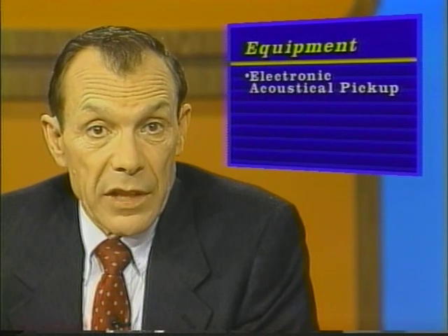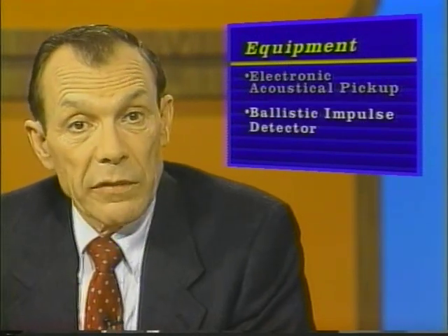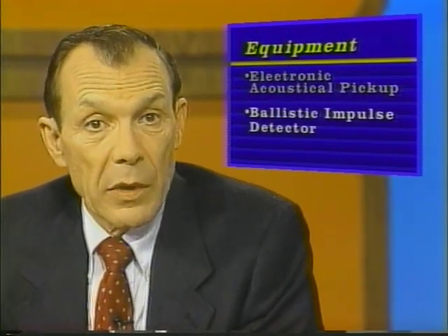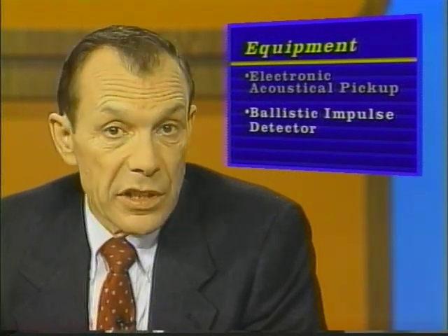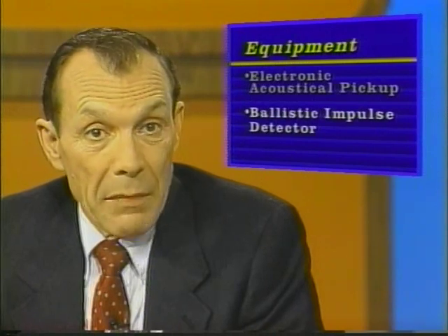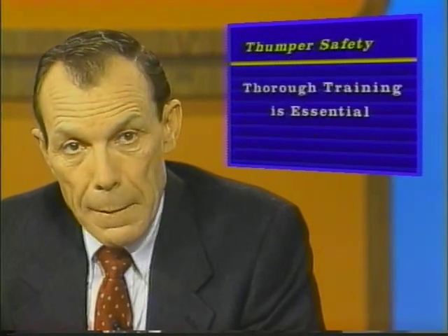Besides the sound of the thump, we can also measure the amplitude of the large magnetic wave surrounding the thumper pulse as it travels the route of the cable. We do this with an instrument called a ballistic impulse or magnetic wave detector.